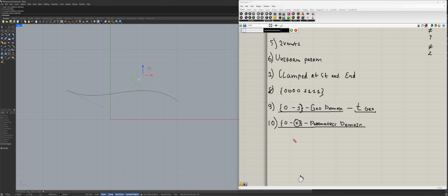And it really depends on a system. It depends on a tool even, and where the object can construct it in space. So this x can be a quarter length. It can be the arc length. It can be the cumulative sum of the quarters between the control points. It can be differences between planar positions between the beginning and the end. It can be anything. System tries to predict, but it doesn't know. So it gives you something it predicts and tells you that you can change that if you want.